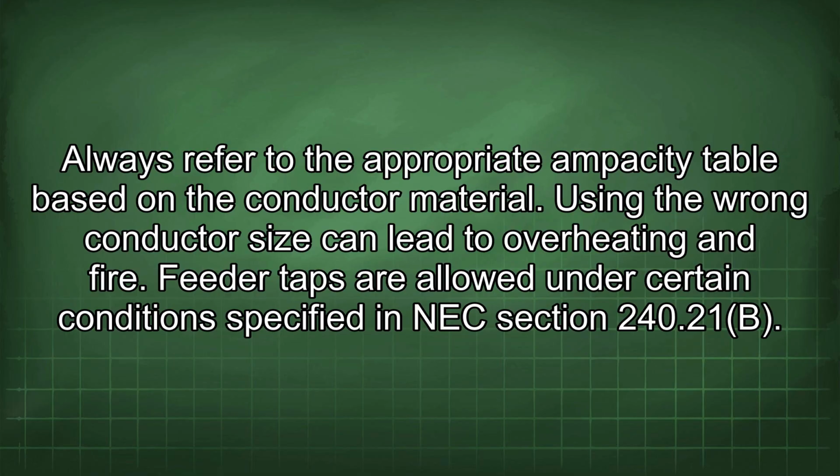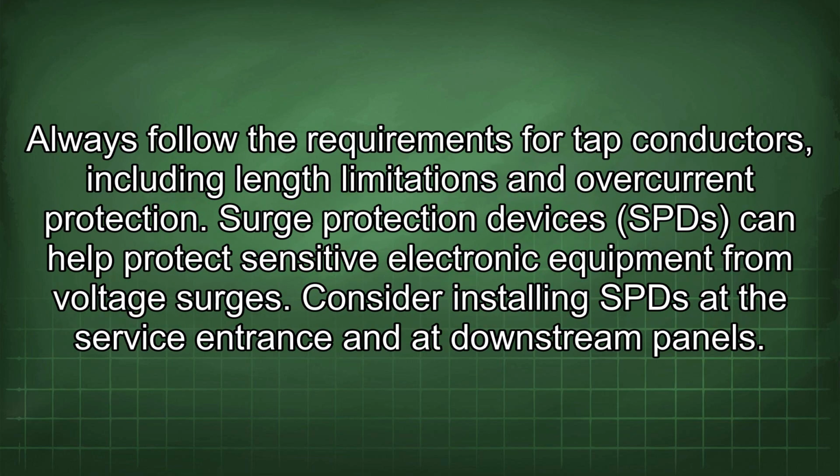Taps are allowed under certain conditions specified in NEC Section 240.21(B). Always follow the requirements for tap conductors, including length limitations and overcurrent protection. Surge protection devices (SPD) can help protect sensitive electronic equipment from voltage surges. Consider installing SPD at the service entrance and at downstream panels.